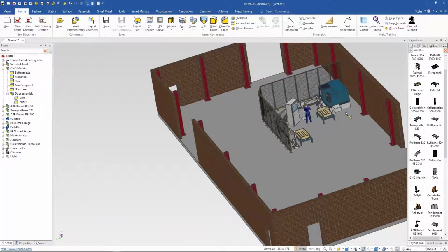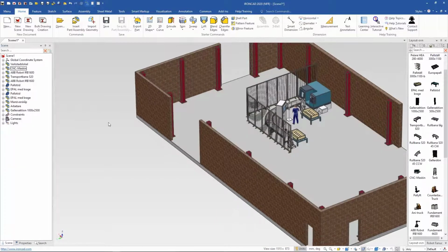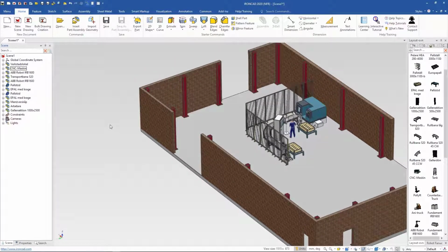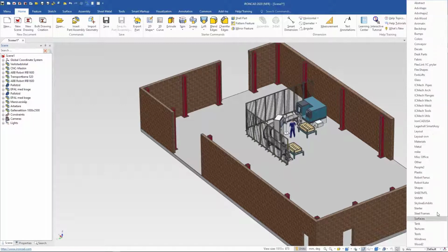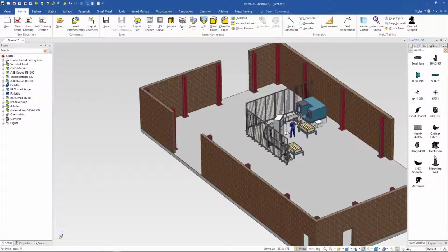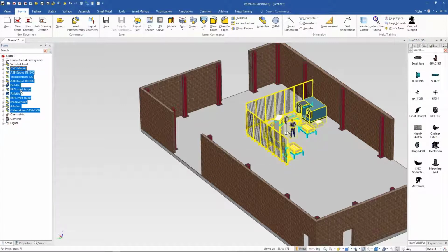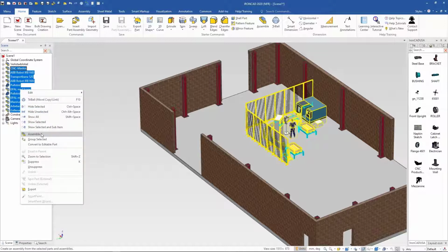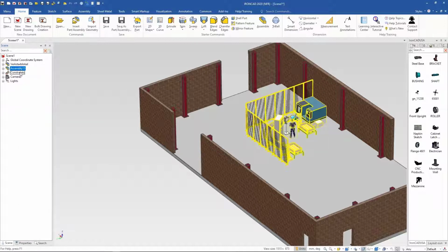Now, if I like what I've done, and this is where I think things are really kind of neat. If I like what I've created, a machining cell, here's what I think is a very, very clever idea that we can do. I like what I've done. I'm going to take this and say, I want you to grab all of this stuff that we've just created, and I'm going to assemble it. All right. So everything is in one assembly, and this is now called my machining cell.